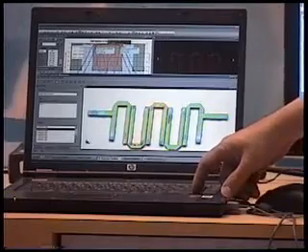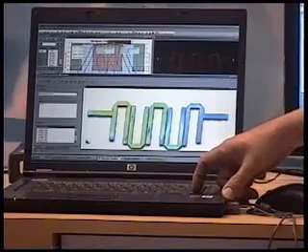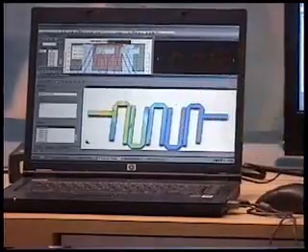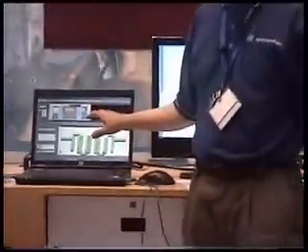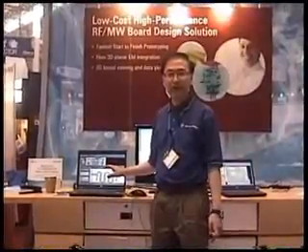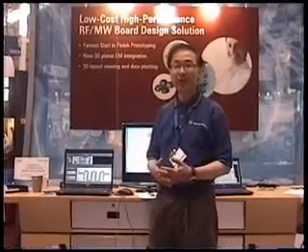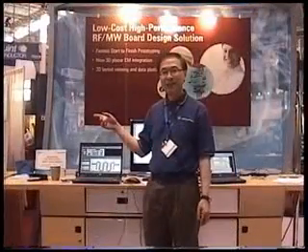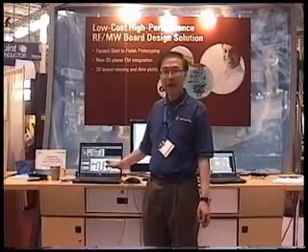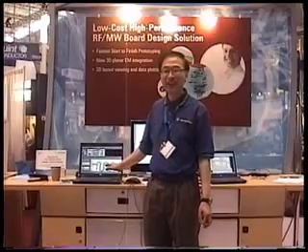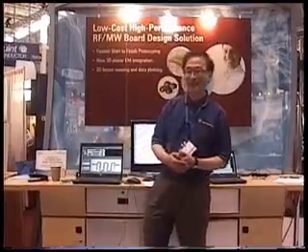So this is a very good way to visualize what is happening in an electromagnetic planar structure by looking at the surface current flow as a troubleshooting or diagnostic tool. So that if you do need to change your layout, you change it and simulate it before you send it off to manufacturing. But let's say everything is well and good and you want to make this into a real prototype. Let me take you to another station to watch this exact filter being manufactured and tested in the same day. In fact, in the next hour, you can get the physical filter in your hand ready for testing. So let's go over there and take a look.